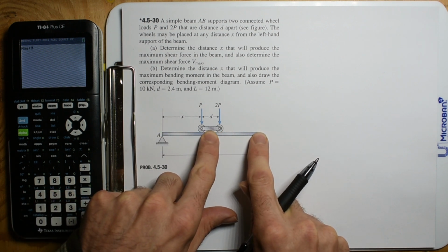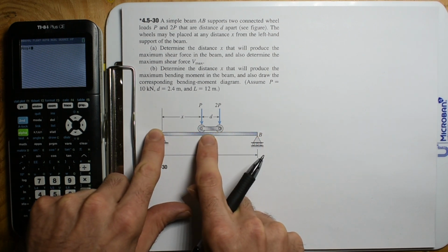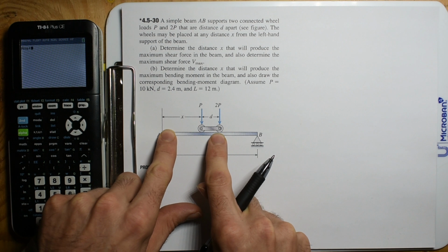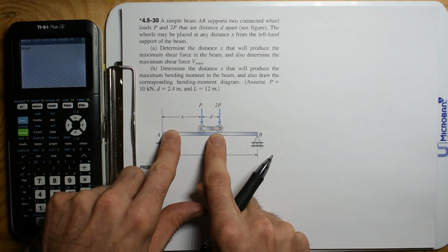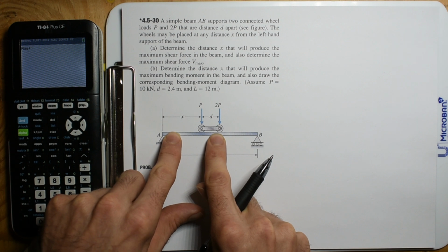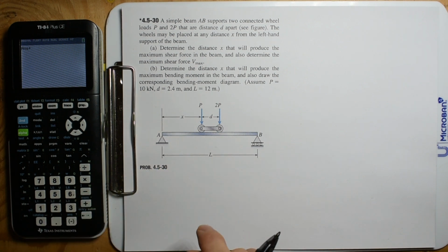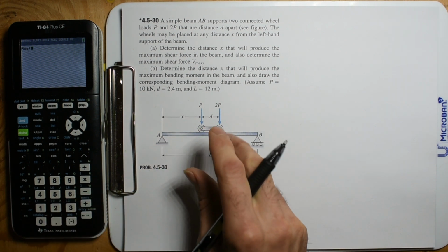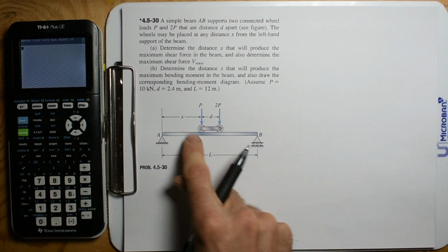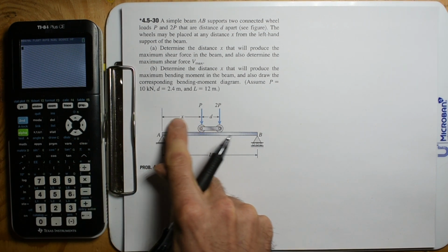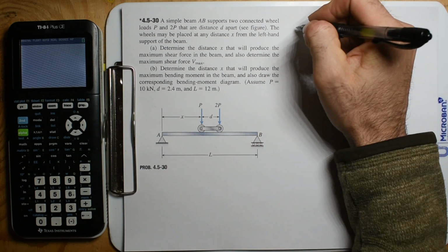If you went the other way, that wouldn't cause it. But if you went in between, if you move this just a little bit, do you generate any extra bending moment because that one's there? I don't know. So this is kind of fascinating. Maybe we'll just learn something by trying to run the equation. So we're just going to pick a generic x, and we're going to sum the moments about B.